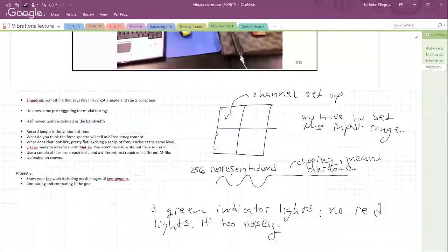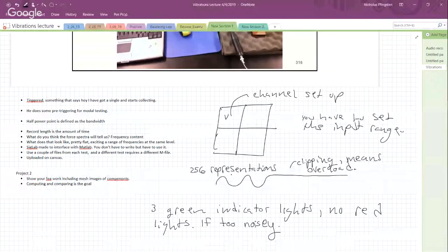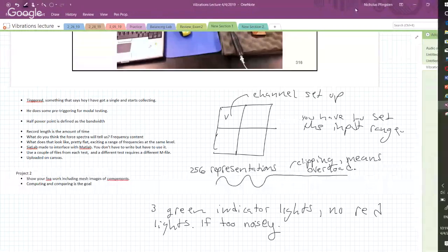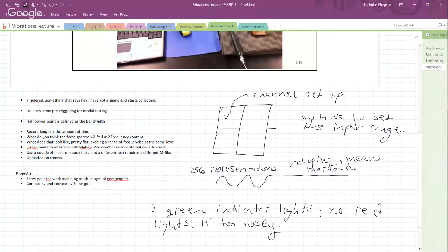And like I said, channel 1 is set to 5 volts. Channel 2 is set to 78 millivolts plus or minus. Next to that, we have something called bias. Bias is something that we use in engineering to define just a low level DC voltage.